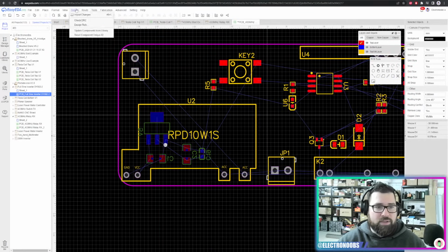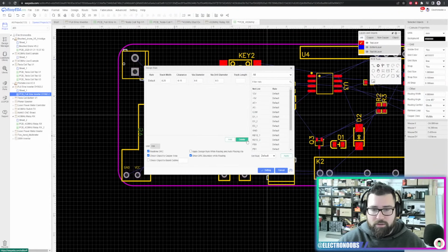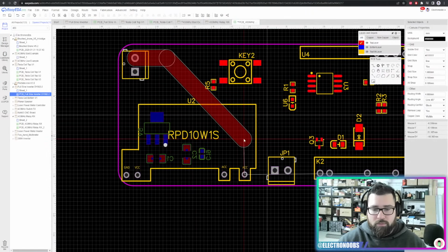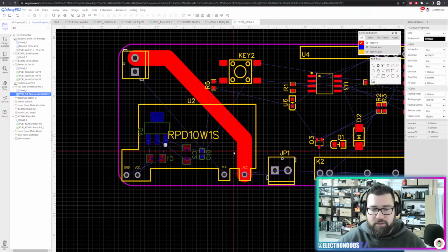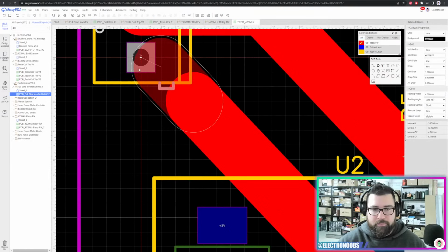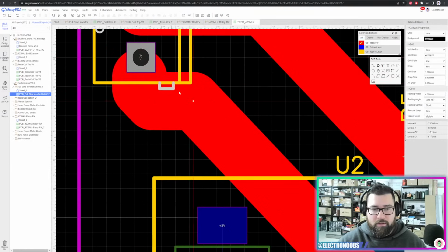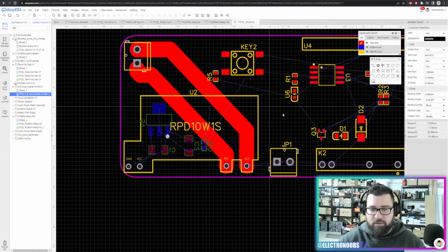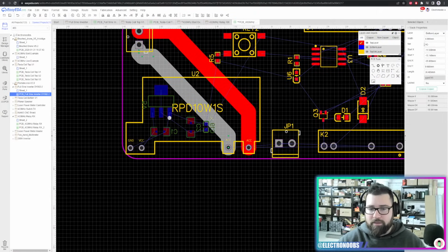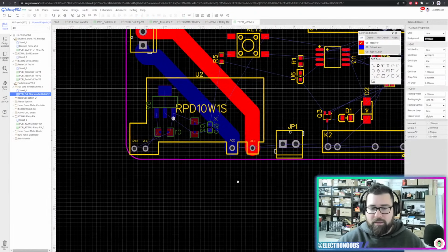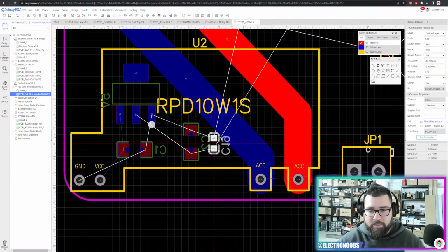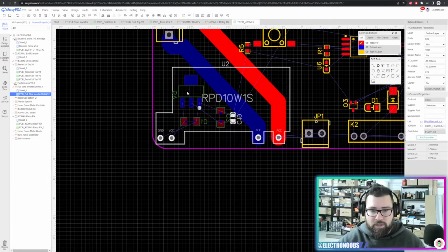and just like that, let me just delete the other rule because I won't use it. So just like that, we go like this. The first connection is made, and the other one something like this. And as you can see, I have my first connection of 4mm. We don't have enough space here, so maybe I'll change this to the bottom layer. So now we have 4mm, and we also have the PCB, which is made of plastic fiber in between. So we have a lot of insulation.